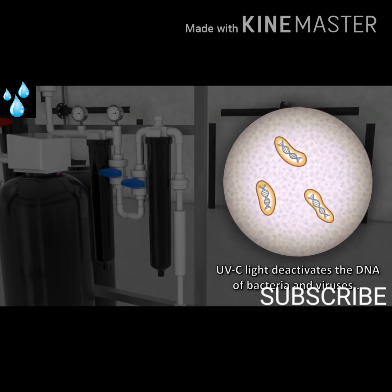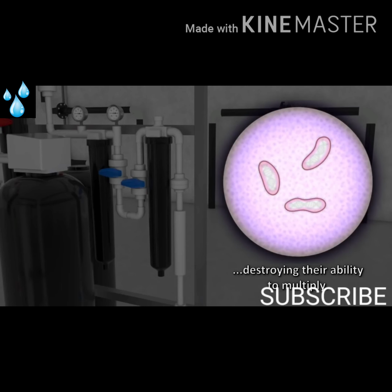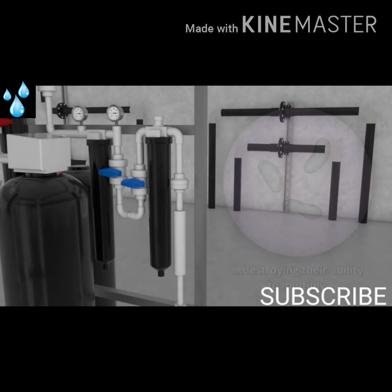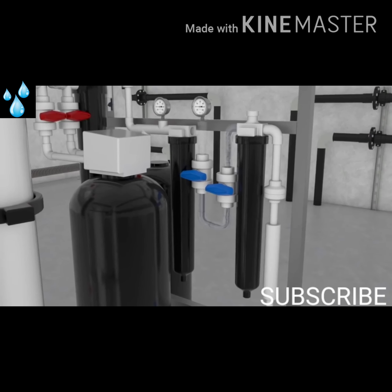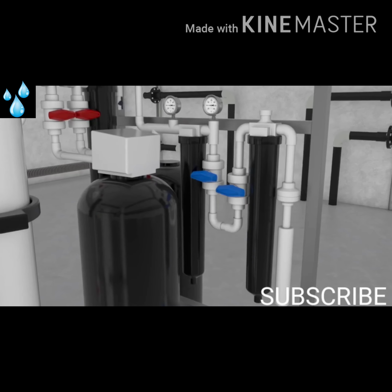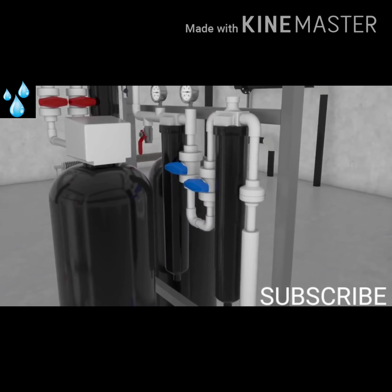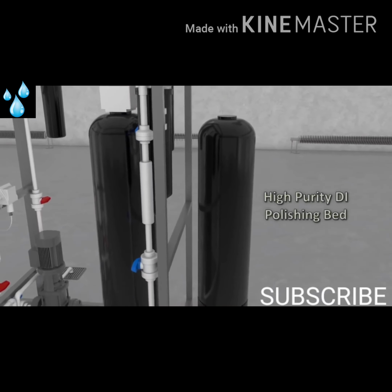Germicidal UVC light deactivates the DNA of bacteria, viruses, and other pathogens, and thus destroys their ability to multiply, which is critical in any process and lab use environment of RO product water. The UV-treated water is passed through a final filter, usually sub-micron, to filter any organic or non-organic matter from the subsequent ultraviolet treatment. In some cases, further ionic removal will be needed to meet the ionized water quality.